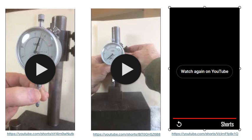It's really fast, so you have to do it again and again in order to see these turns in both dials, the big dial and the small dial. Then you will place the object of interest to get its height, after gauging with the gauge block.